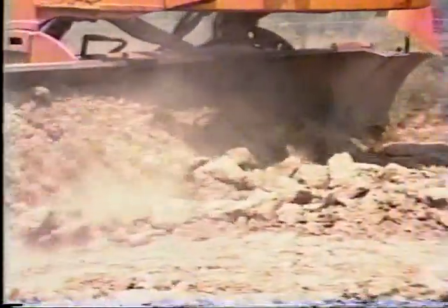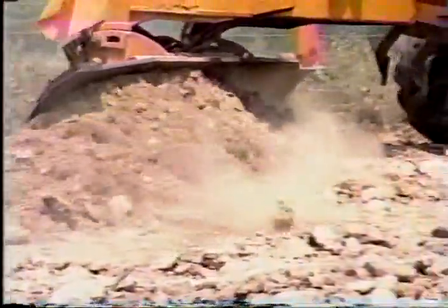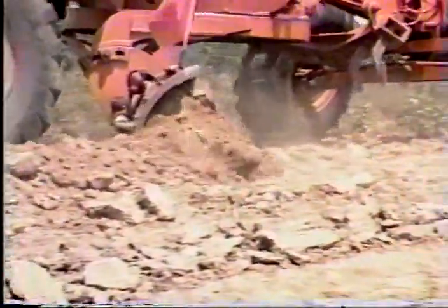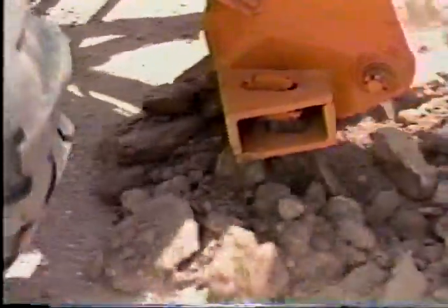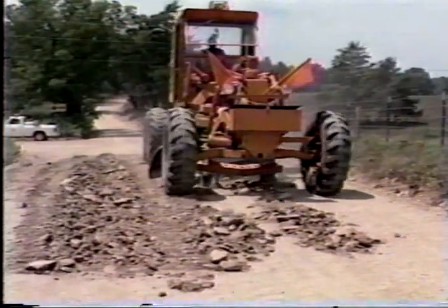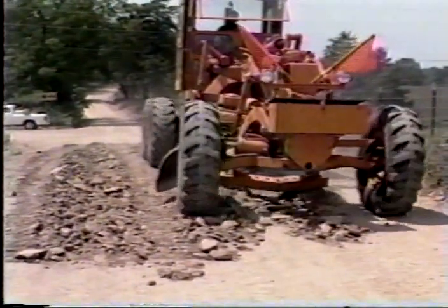In reshaping, the crust that forms what is left of the old wearing surface must be broken up and the aggregate base remixed to get a proper blend of fines and base material. This process oftentimes involves the use of a scarifier, but new material may need to be added, particularly in extremely rough or washed out places. Before we discuss the recommended procedure for reshaping, let's first review the basic components of a gravel roadway.